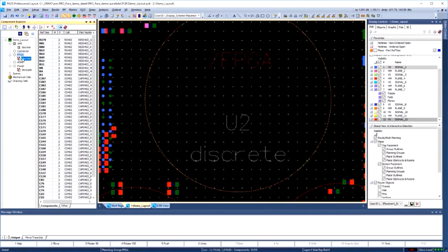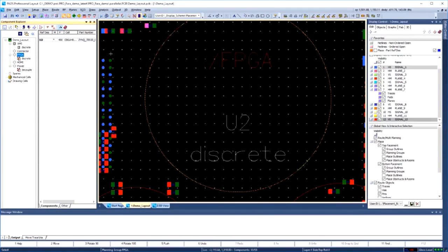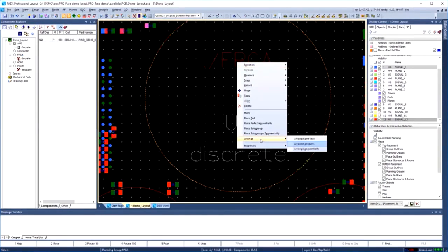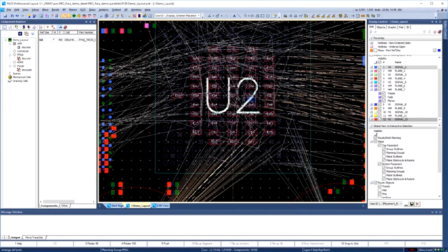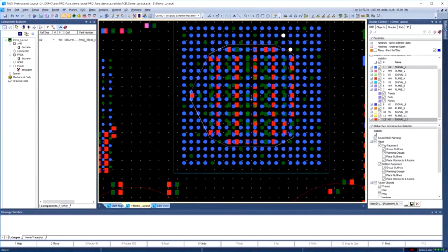You can place by hierarchical subgroups, or arrange all groups based on all layers or just one layer. The subgroups can be set to be placed on specific layers and angles. The placement algorithm uses Constraint Editor part clearances and the part grid. Setting a subgroup up for decoupling capacitors on a large ASIC or FPGA chip is a really handy trick to control placement to minimize the rearrangement of these decoupling capacitors. Just use a larger grid to spread out the components.